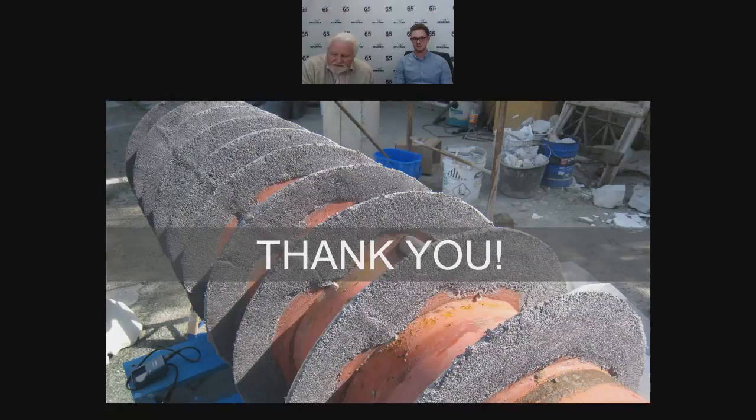Generally speaking, for slurry pumps, the substrate is not your run-of-the-mill cast iron or steel. It's generally some kind of hardened chromium steel, chromium nickel steel, something like that, which is extremely hard. So it might be difficult in the first instance to actually grit blast the pump to get the minimum required profile. So provided you can get the profile, then yes, you could use our materials.